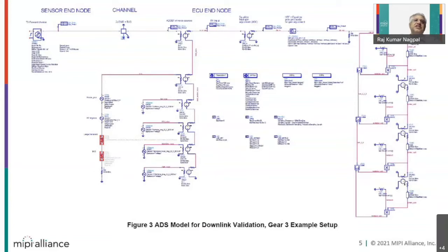Okay, and this is like a gain block. This is your filter which I shared with you. Then you may have a CTLE, and this is your DFE implementation. And by the way, you will tune the DFE coefficients for your eye opening.